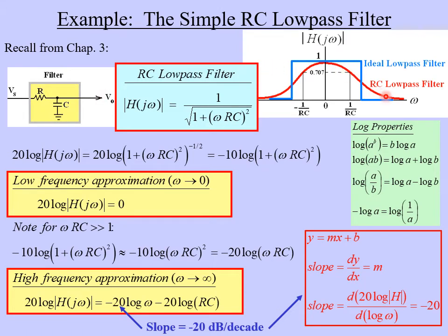At higher frequencies, though, remember a capacitor acts more like a short circuit. And so this is a voltage divider circuit here, and the low impedance of this capacitor at high frequencies pulls this output voltage down towards 0. So as a result, at high frequencies, the filter basically blocks any signal coming in. It basically gets multiplied by something very close to 0. And again, this is not a perfect filter, but you can see it does the job. It acts as a low-pass filter.